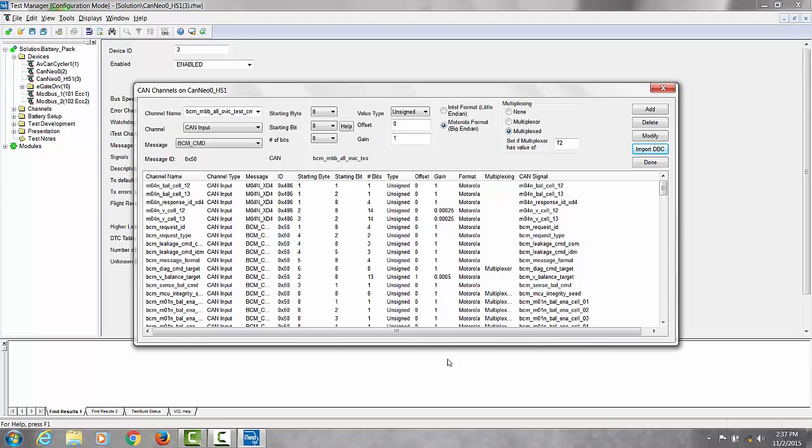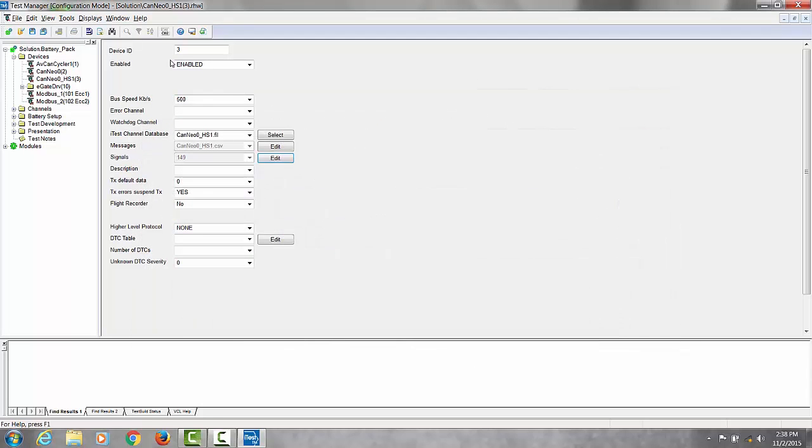We now have our list of CAN signals, but, and this part is important, we want to map these signals to our BTS channels. This will become very helpful down the road. By mapping the channels, BTS can parameterize these values, enabling you to use the same test schedules from one test to another. You only have to do this mapping once for each battery management system. Save your configuration, and it will save you a lot of time down the road. So we'll exit out of here.